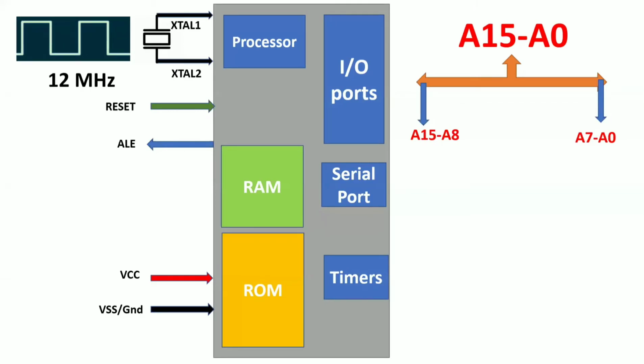Okay. Next, there is a data bus. Now what is the size of the data bus? 8-bit, right? Now the Intel engineers are very intelligent people like you. What they were thinking is that during the execution of the program, you require the address first. Later we will use the data. Okay, before knowing the address, we cannot get the data, right? That means first I will use the address bus, later I will use the data bus. That means I am not using the address bus and data bus at the same time. So this is the one idea.